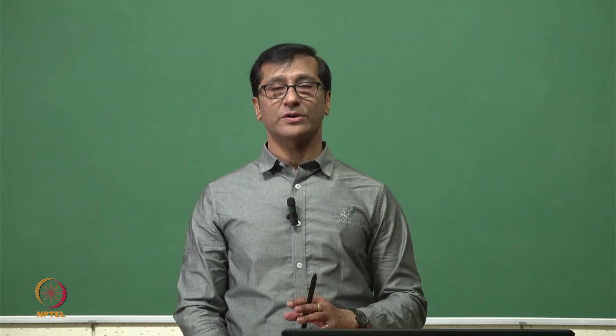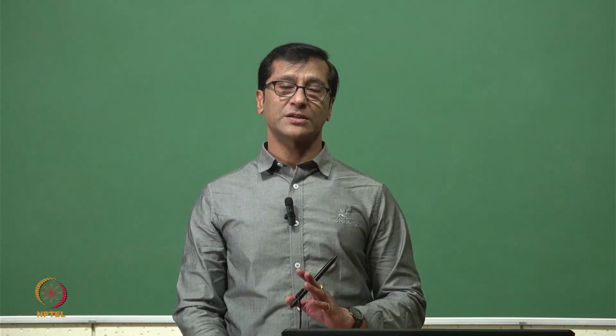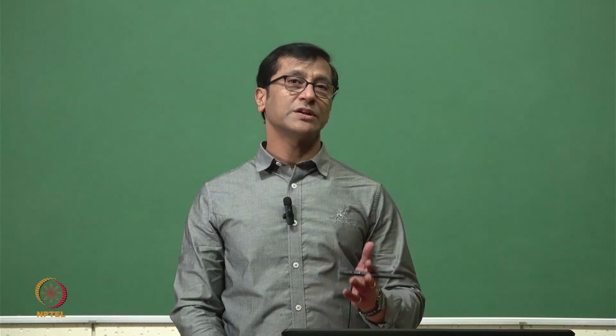If I want to really summarize whatever I covered, I say that in the PF curve what we have shown, there are two important terms that we call potential failure and functional failure. And if there's a functional failure, we should stop utilizing that component. However, a potential failure is a kind of indication that there is a possibility of failure. The failure has not yet occurred, but there's a possibility of the failure, and it is still in working condition.